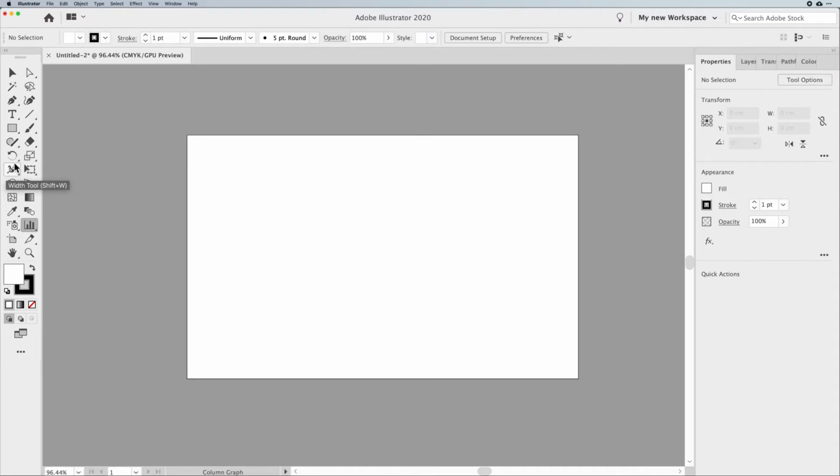But you'll notice that a lot of these have shortcuts associated with them. And when we go through these videos, I will tell you what those shortcuts are repeatedly, because the more you learn the shortcuts, the better you're going to be in creating with Illustrator. So anytime that you want to use a set of tools here, say drawing shapes, something that we do all the time in Illustrator, we're constantly creating shapes and lines. You'll notice that when I click and hold, I get my entire set of shapes flying out here.